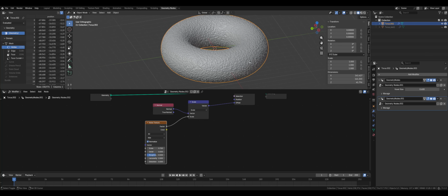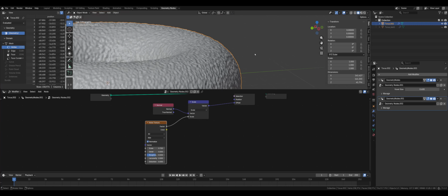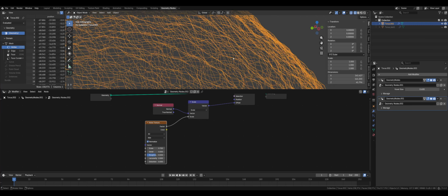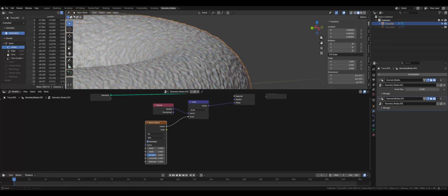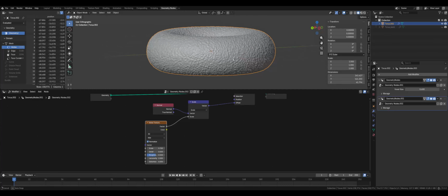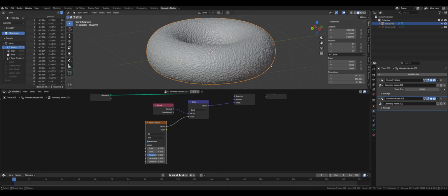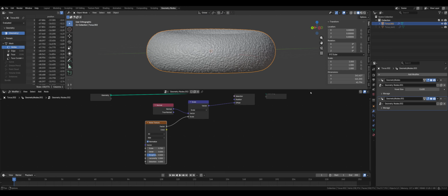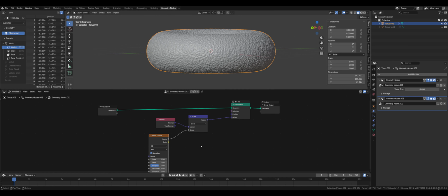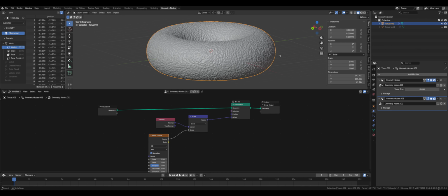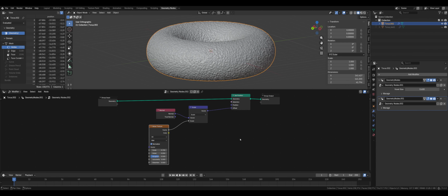That would be the simplest implementation of adding a surface texture. As you see, it is in the actual geometry. So if you exported this right now as an STL or OBJ or something and took it into your slicer, you'd be able to print it. Now, at the scale that it is, it probably wouldn't work so well on an FDM printer, but for a resin printer, it would work really well.